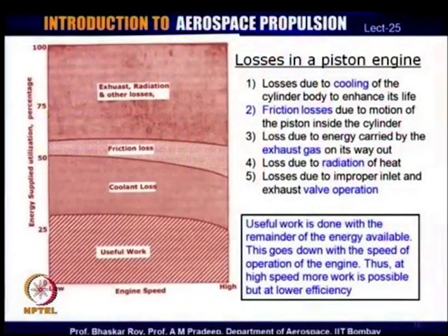limitations, and if you have to provide them with certain amount of lifespan or working, which is often in terms of thousands of operational hours, then it is necessary that these bodies are cooled on a continuous basis to lend them a certain respectable amount of life. As a result of which, a goodly amount of heat is actually lost through the cylinder body through the process of cooling. This cooling is absolutely essential for the life of the engine, but it affects the continuous operation of the engine in terms of its actual power supply efficiency.